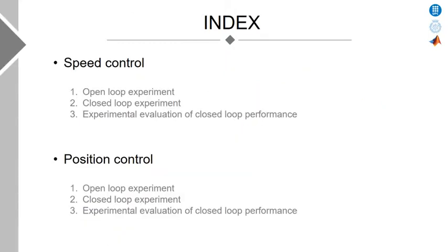First, we will analyze the response of the motor in open loop, taking as output the signal of the tachometer dynamo, with which we will obtain the mathematical model. Next, we will close the loop with a proportional controller and analyze the responses for different values of Kp. Finally, the performance of the plant will be analyzed, sampling it with different sampling periods. The same steps will be followed by taking the potentiometer signal as output.